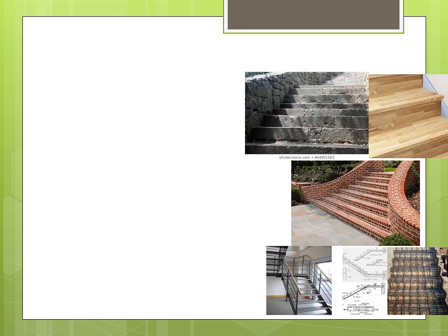Okay, so we have discussed about the stairs based upon their shape. Now based upon the material, as you can see, the stone stairs are generally used in approaches to basements, heating chambers or in ashlar masonry buildings. Stone stairs are used at places where ashlar stone is readily available. Next is brick stairs. Brick stairs are not very common except at the entrance. Brick steps need frequent maintenance. The material used is brick, as you can see from the figure.